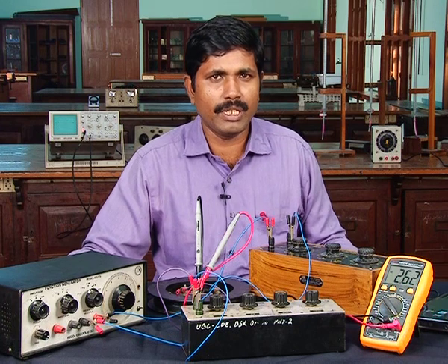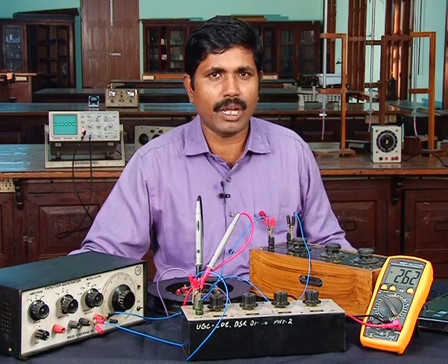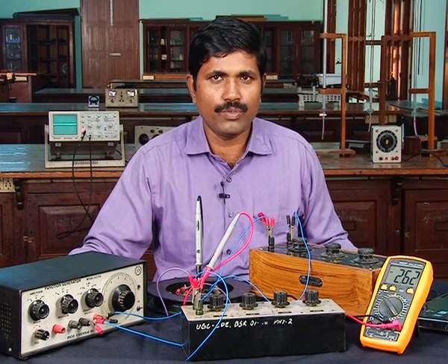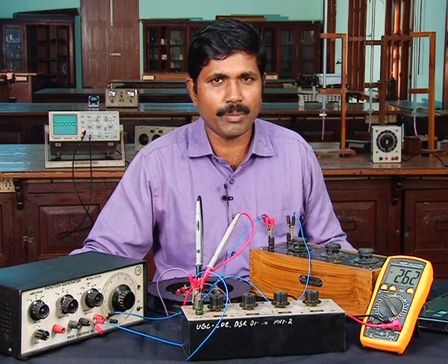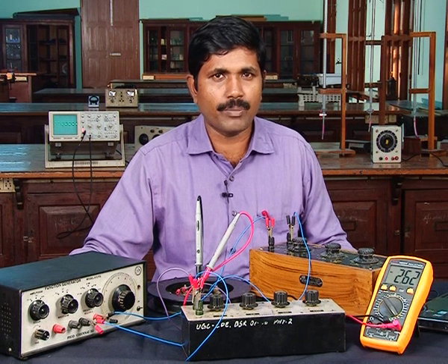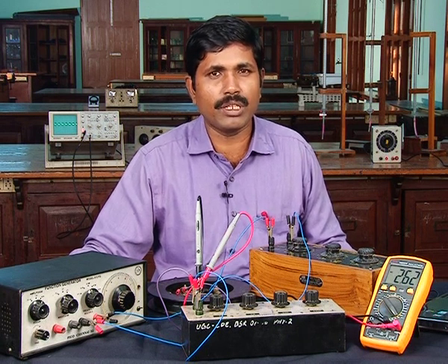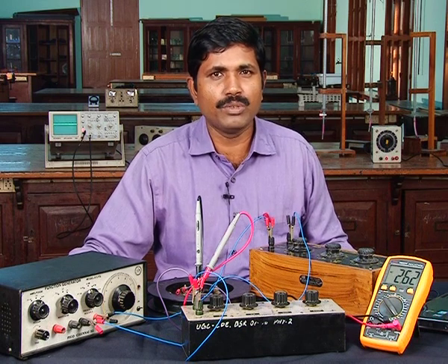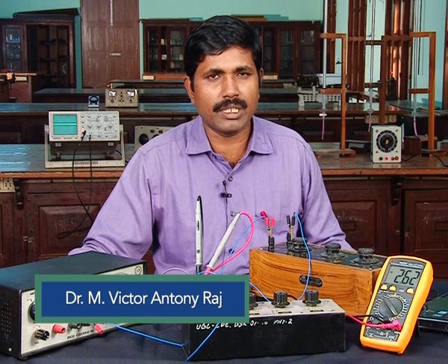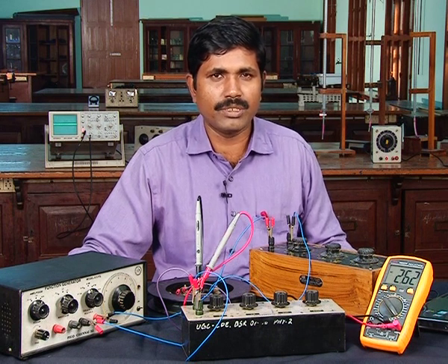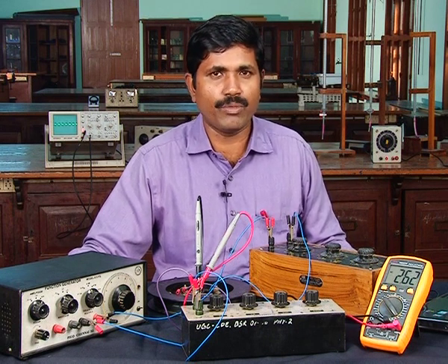These circuits are applied in receiver circuits or acceptor circuits. If we keep the values of inductance, capacitance and resistance as variable, automatically varying or parameter dependent varying according to the incident frequency, the values of the inductor, capacitor and resistor will vary. So, it will adjust its bandwidth, it will become a narrow bandwidth circuit or wider bandwidth circuit.